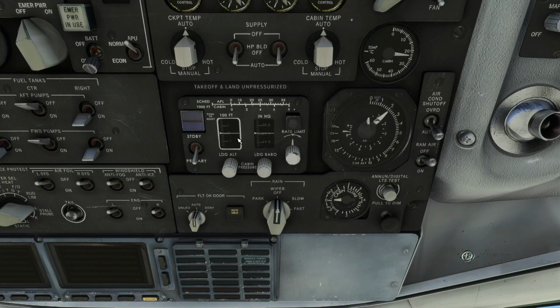Just in case we have to come back in an emergency, the pressurization will easily be set for wherever I'm going. A lot of SOP is just to set this to the arrival field. Whatever your SOP is, that's fine, but do that. And then over here, you tell it whatever the barometric pressure is of that field. So if you're going to set your departure field, make sure this is set to your current altimeter setting.